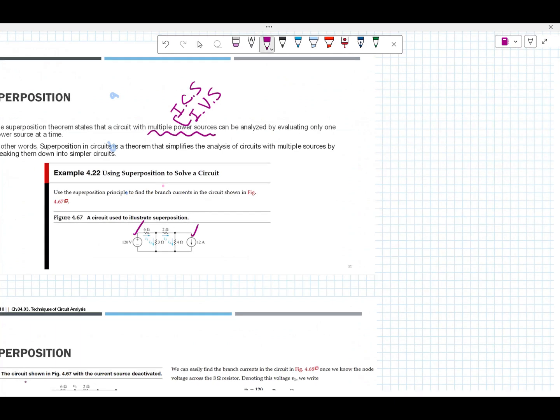So first of all, we learned before, that plus minus was the short circuit, and the open circuit was for the current source. So for example, we keep the voltage source, 120 volt, just the one, and the independent current sources we make an open circuit. The independent current sources keep staying there when we consider the voltage sources deactivated, and the independent voltage sources become a short circuit.